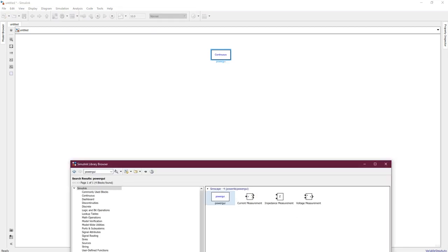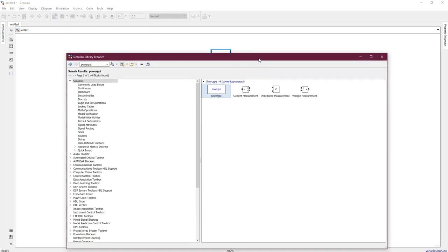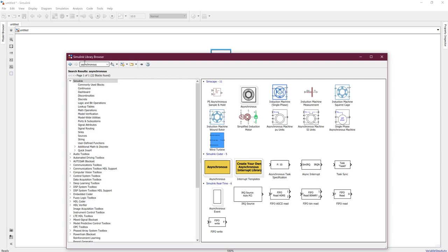So now again to the Simulink library. Then we need to add the asynchronous machine, synchronous, enter. Okay, so let's see the Simulink, Simscape. Okay, the Simscape. So let's see where is the induction machine, asynchronous machine per unit values. Okay, this is our synchronous machine. So this is inside the per unit values.